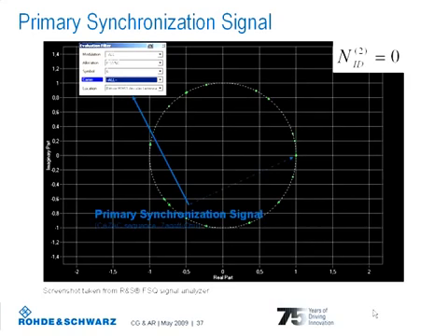This helps to do matched filtering, finding the right sequence used for the primary synchronization signal. As Christina explained, 72 subcarriers translate to 6 resource blocks, as 12 subcarriers form a resource block in the frequency domain. With 15 kHz subcarrier spacing, the occupied bandwidth around the carrier frequency is 1.08 MHz.